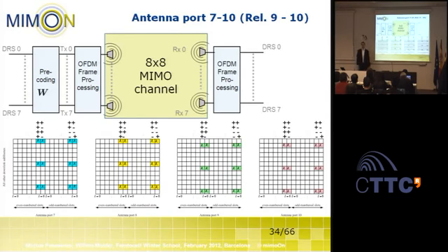On top of this, to further separate these 2 orthogonal resource patterns, we use CDMA, so orthogonal sequences are used to further distinguish different antennas. For each of these resource maps, we can use orthogonal sequences to further distinguish between 4 antennas using this scheme and 4 antennas using the other scheme. This can be separated using this orthogonal code, indicated here as plus, plus, plus, minus.